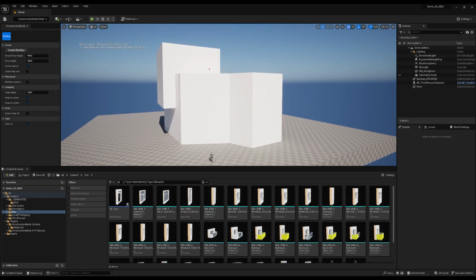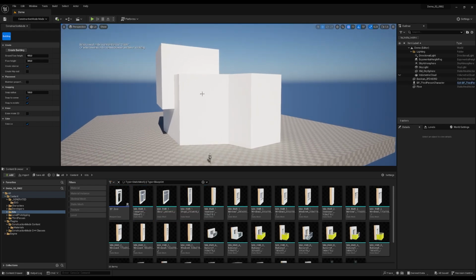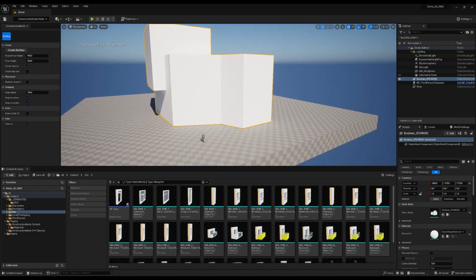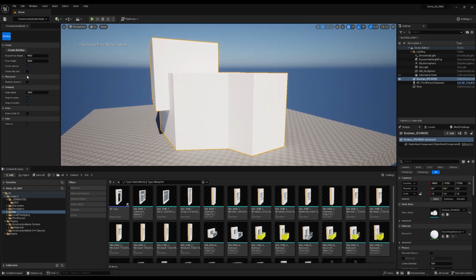You can select one or multiple buildings in the scene. After selection, you have the option to set the ground floor height, the floor height, and whether to generate floor meshes inside. So if you want to create interior, you have to check this. And to either use sloped or flat roofs. So first, let's create this building with interior and with a sloped roof.